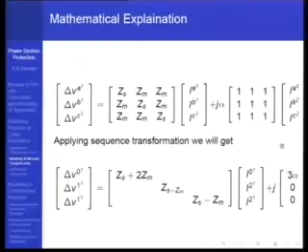Now this is in the phase domain. The moment I transform this into the sequence domain by doing a T inverse A T type of transformation, you would see that I get Zs minus 2Zm, Zs minus Zm, Zs minus Zm, the standard ones, plus 3 alpha here. This is cut here, it's not fully shown; you can check in the web course. The first term is only 3 alpha and all other terms are 0. So the coupling only comes with IA0, not with IA1 and IA2. You can show the same thing using sequence transformations also.